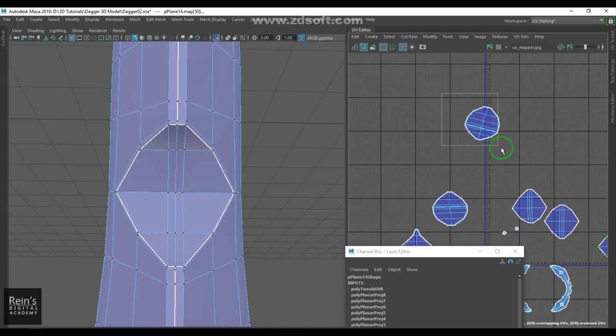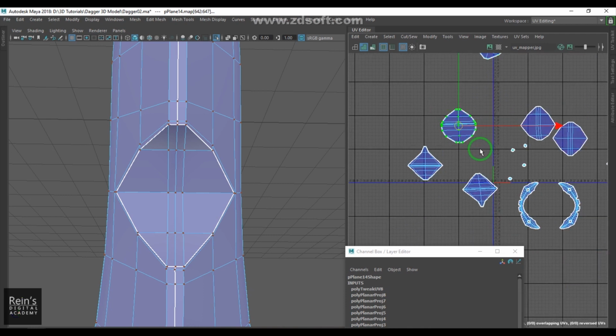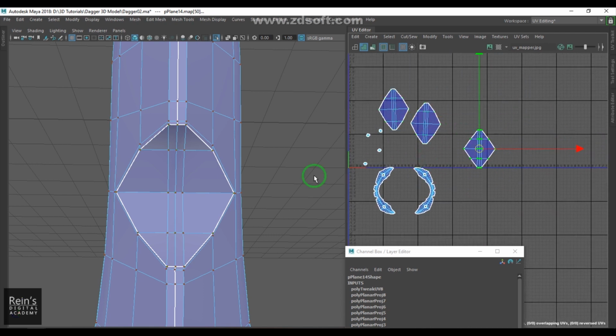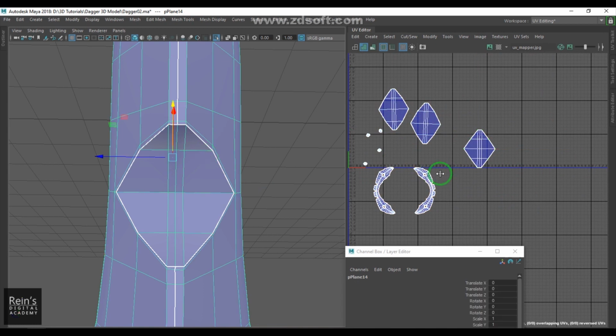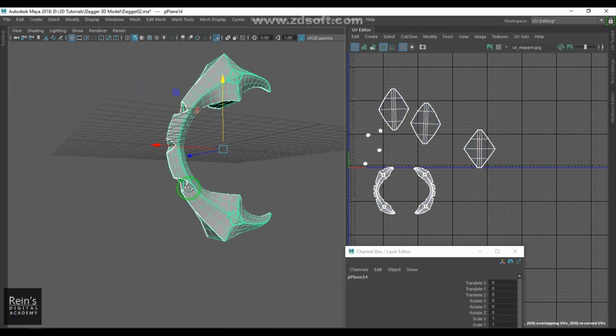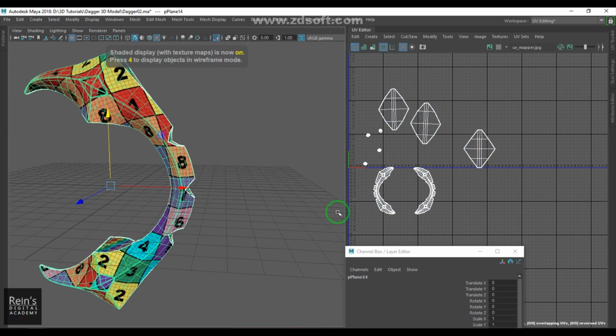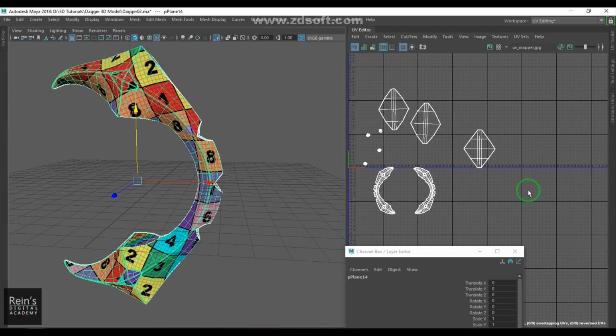so all are in blue color, just need to select and then unfold. Unfold tool I've used. To repeat that tool I need to press G on the keyboard. Okay, then this blue shade, if you want it to go away, put your cursor in the UV editor, press 4, press 5 4 to switch, and then press 6 to see the textures, but make sure that where your cursor is located is very important.